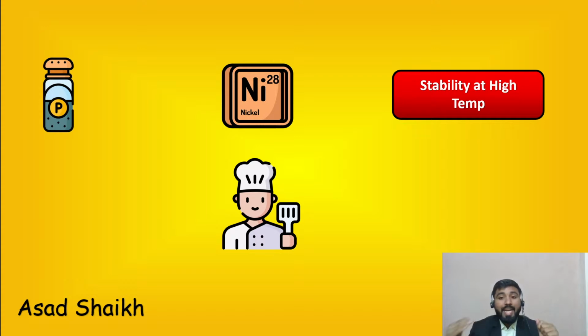Another important thing is the trim material. According to me, do not be stingy on the trim material. Select the best, because the trim is going to experience the highest amount of velocity, dP, everything. So the trim material should be at least the same as or higher than that of the piping valves. On trims we will go in depth hopefully in coming sessions.